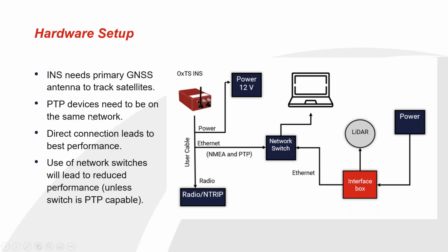PTP devices also just need to be connected to the same network, so you just need an Ethernet connection between your INS and whatever device you want to be synchronized. Direct connection leads to the best performance. So if possible, directly connect the INS to your PTP slave.